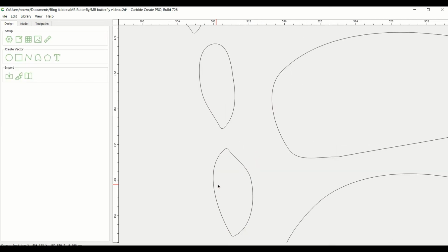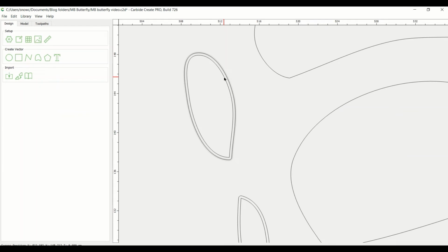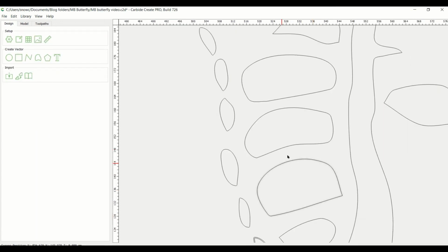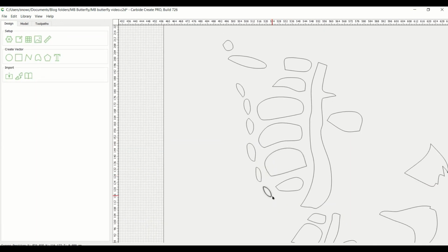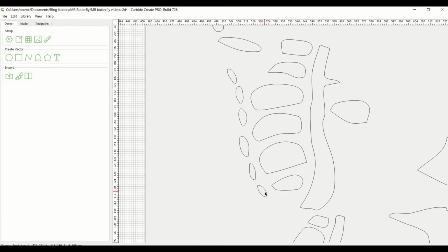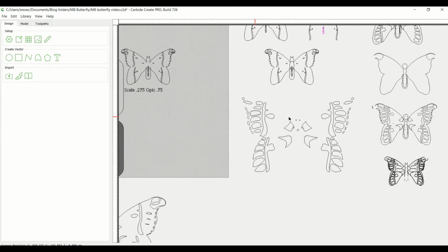And we have to change it, so we're going to be using a 1/8" ball nose bit, and if we make them too small, it just won't carve in any detail. So these will carve little dents a little bit because they're bigger. So you might want to change a few things around like that. You can decide whether you want to scoot them in or scoot them out. So that gives us our dots.